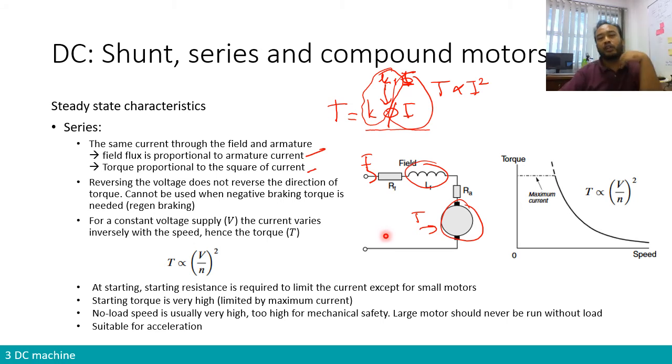So if you are descending a slope, for example, when the back EMF is higher than the voltage supply, you will experience a certain braking, so that the acceleration of your vehicle is going to slow down. It is just like in your normal ICE vehicle, when you shift down to lower gears going down a slope, you experience a certain braking by the gear. So it's the same case in an electrical machine. You will experience a certain braking by the machine.